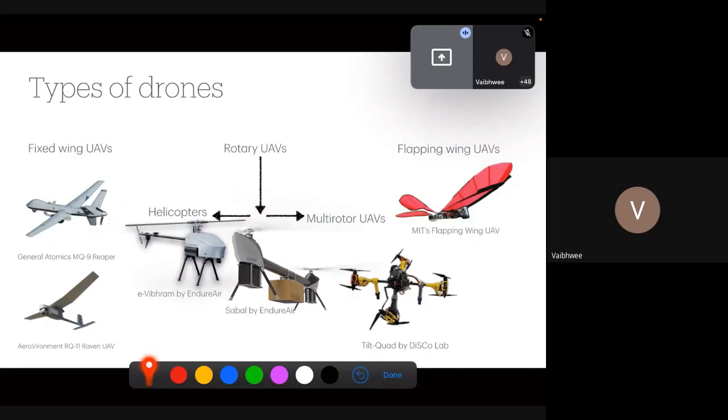Now in this case, when the rotor starts spinning about the vertical axis at a certain speed, the blades that you see here, because of their movement in the air, will generate lift, and that is how the helicopters take off. The tail rotor is primarily used for attitude control, so it contributes to some part of the attitude control, but it is the main rotor which is primarily used for all the translational and rotational control of this helicopter, of course along with the tail rotor.